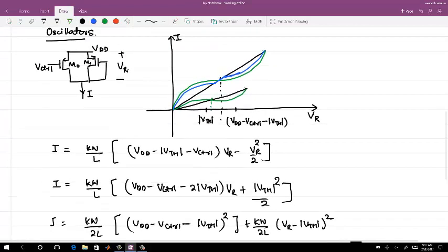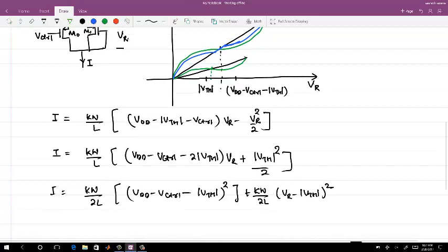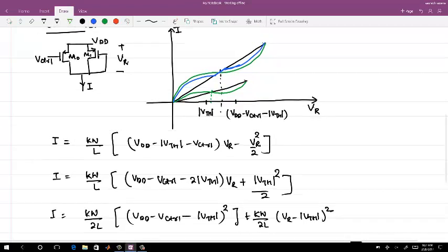So the thing which we started was that this kind of loading has a symmetric nature around the center point, and the symmetric nature, or odd symmetry, around the center point helps in improving the power supply rejection ratio. One is the power supply rejection ratio, another is the loading itself: your R1 and R2 do not change, they keep the average swing the same.